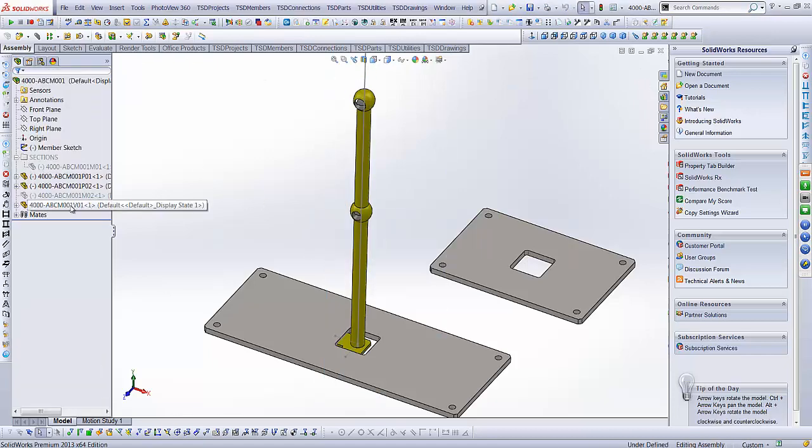Now you'll notice that there is a naming convention at play. I did select a vendor item, and the item that's come in has come in with a V. Now that's a naming convention that we use. I'll cover that in another webinar. It's important that you use it. I think there's 4 different letter conventions: P for plate, V for vendor, D for dummy, and M for member.